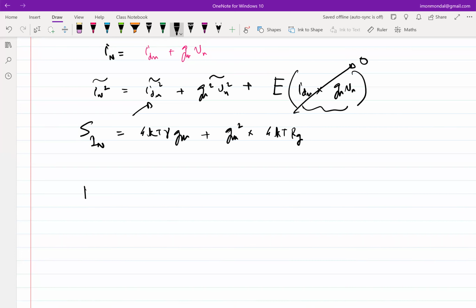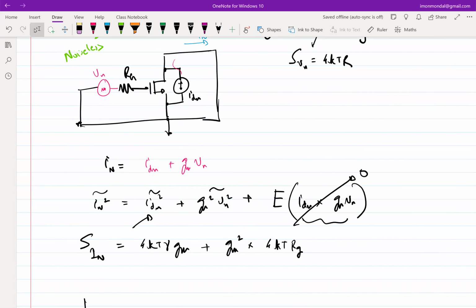Student: While calculating the noise, why aren't you worried about the gate capacitance? Yes, I have not taken any capacitance till now. Obviously, if there is a capacitance, it is going to shape the power spectral density, right? So in that case, we have to take that into account. We'll come to that. Student: Like placing V_N and R_G the other way, that will not shape. I didn't understand. V_N at the gate and R_G before that? No, these two come together, right? Student: You cannot. R_G left and V_N right.